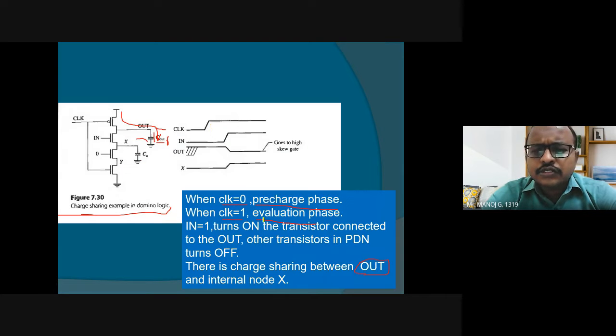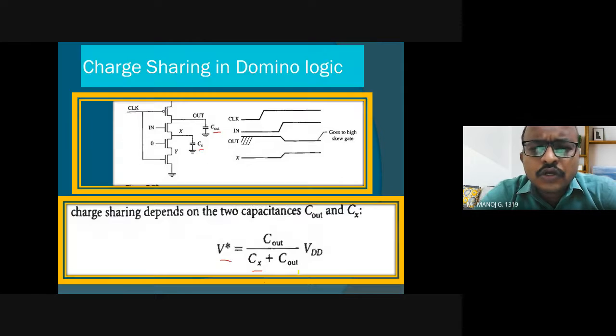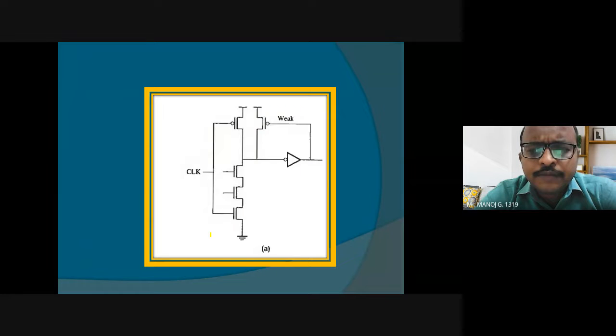Charge sharing, we all know, takes place in the two phases, and the charge distribution is not proper. Because of this improper charge distribution, the device might get a different output, not the expected output. So this has to be negated, otherwise your logic will go wrong. This charge sharing phenomenon has to be made proper. So in order to do that, we evaluate the charge sharing. This is the formula used for defining that, and then we go on to see how to overcome that.